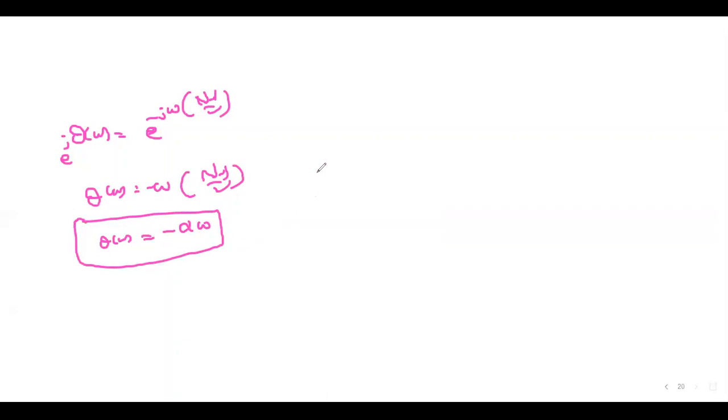So therefore, if you draw the magnitude response H cap is equal to summation n equal to 0 to (N minus 1)/2 of a of n into cos omega n. So this is a cos function, and the cos function varies between plus and minus.